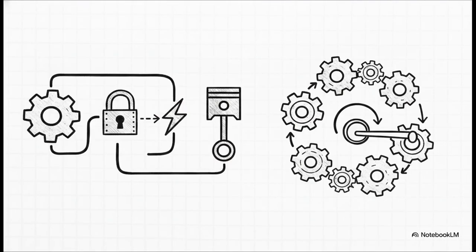This system perfectly highlights two essential automation principles you should definitely take away from this. First, conditional permissives. Sequential automation relies entirely on logic gates. Events cannot trigger out of turn because earlier states, like C1 hitting 10, act as required permissives for later states, like C2 starting its count. Second, self-sustaining logic. True automation requires meticulously designed auto-resetting loops that clear their own memory and physical states to run infinitely without any human intervention.